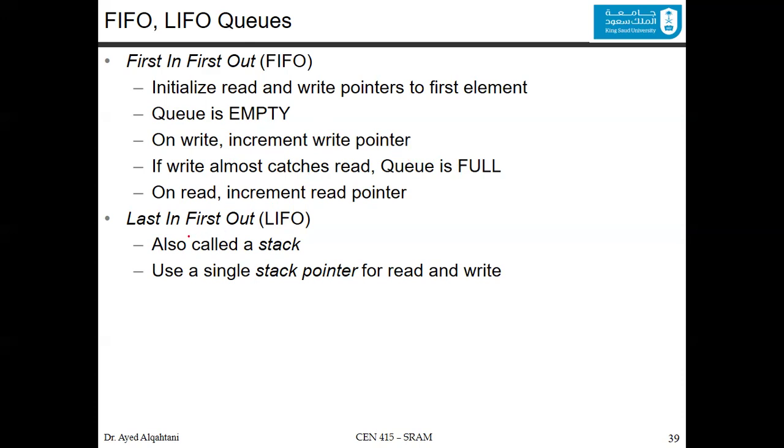For the LIFO, the last in, first out, is also called a stack. We have the push and pop operations, and we use a single stack. At the top of this stack is called a stack pointer, and we use the same pointer for read and write.